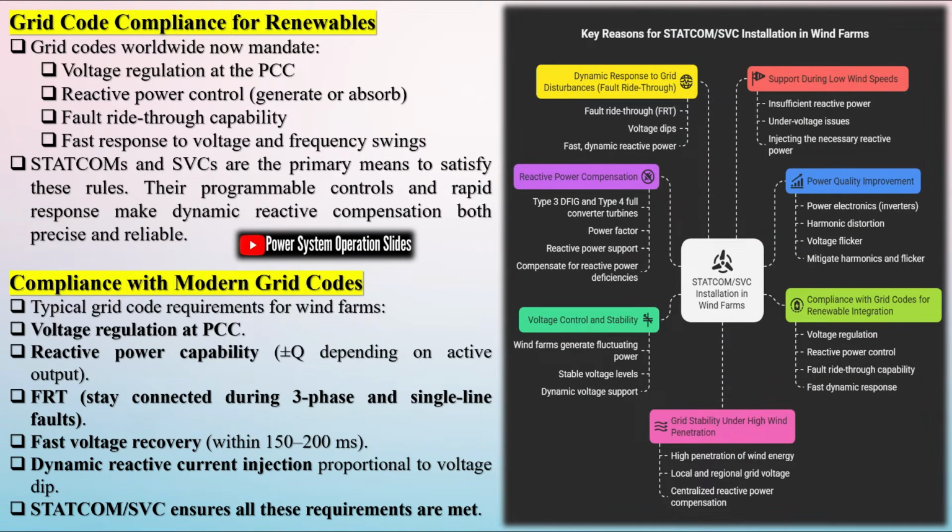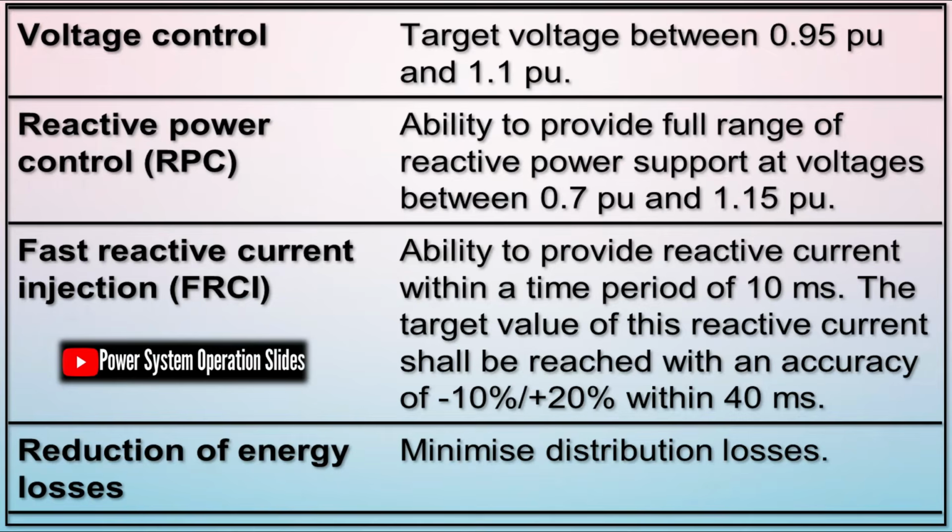Conversely, when its voltage is lower than the grid's, it absorbs reactive power, acting like an inductor. If both voltages are equal, no reactive power is exchanged. This dynamic control allows the STATCOM to respond instantly to voltage deviations caused by faults, load changes, or other disturbances. By adjusting the magnitude and phase angle of its output voltage, the STATCOM helps restore grid voltage to desired levels, ensuring stability and compliance with operational standards.